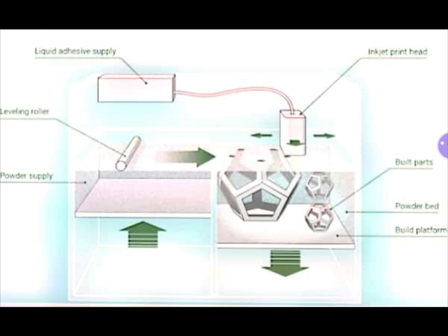Depending upon the data, depending upon the model that is going to be created, and depending upon how the slices are made, the binder material is deposited on the surface of the powder, and this powder binds within a fraction of a second.